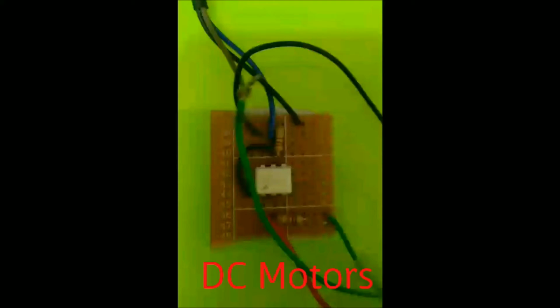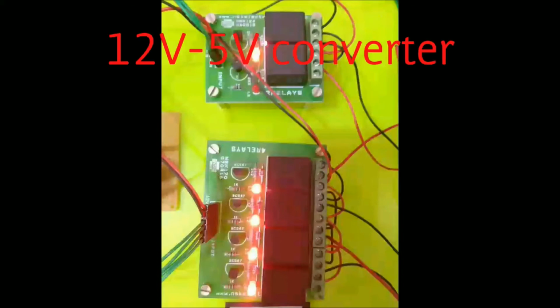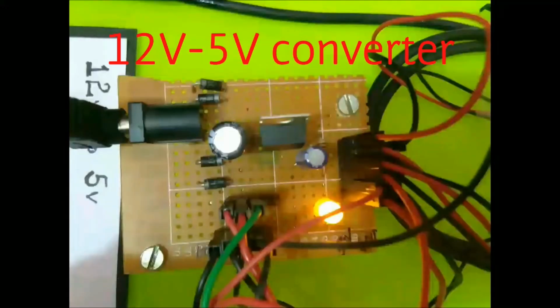There exist three 12-volt DC motors of 60 rotations per minute for swiping action, lifting action and rotating action. 6 12-volt relays are used for anti-clockwise and clockwise rotation of the motors. A 12-volt to 5-volt connector circuit is used to provide separate 12 volts and 5 volts power supply.